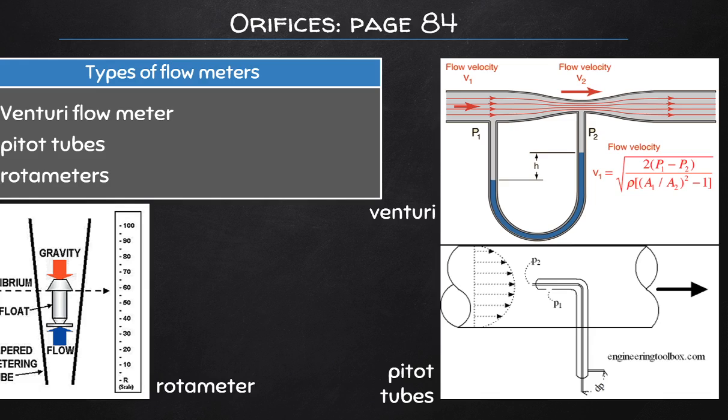Magnetic meters, I've also seen in industry, use a magnetic field to determine the flow rate, but these only work for certain types of fluids and have additional requirements for pipe layouts, for example. You can't have pipes running parallel to each other too closely, because the flow in the other pipe might interact with the magnetic flow meter in the pipe that you're trying to measure.